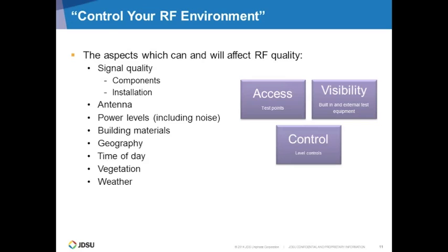And the third part of testability is control. For most, it comes down to the level controls. What control do you have over the device under test or the system to control the levels? But it also has to do with different test modes. You can control the device to push it to full power to make sure that under full power load conditions the signal will still maintain its signal integrity.